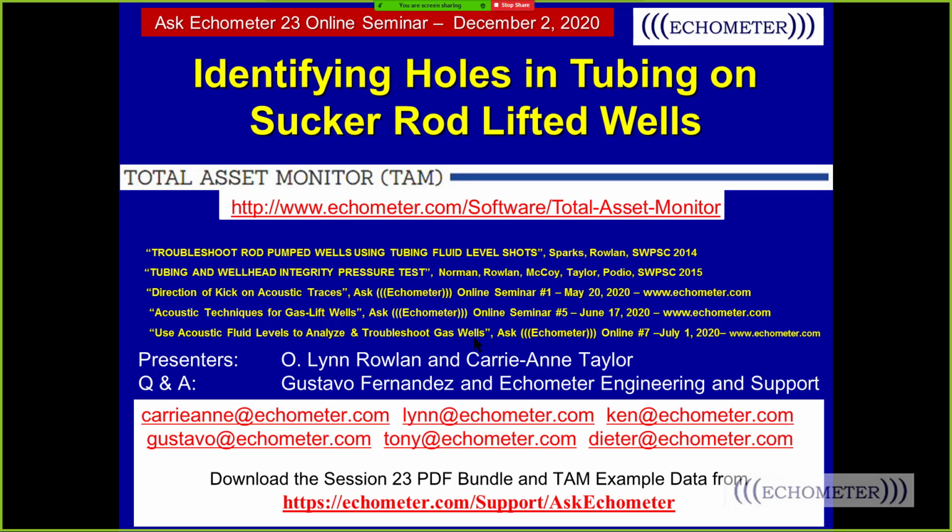So in some cases, if you're experienced and you have multiple shots in a well over time, you can compare shots and see changes that could indicate scale or corrosion. But it's not very easy. It's really hard to do because it takes multiple shots over time or something unique about the acoustic trace that indicates a problem. And usually corrosion, scale and paraffin aren't over a small area. They're widespread in the wellbore.